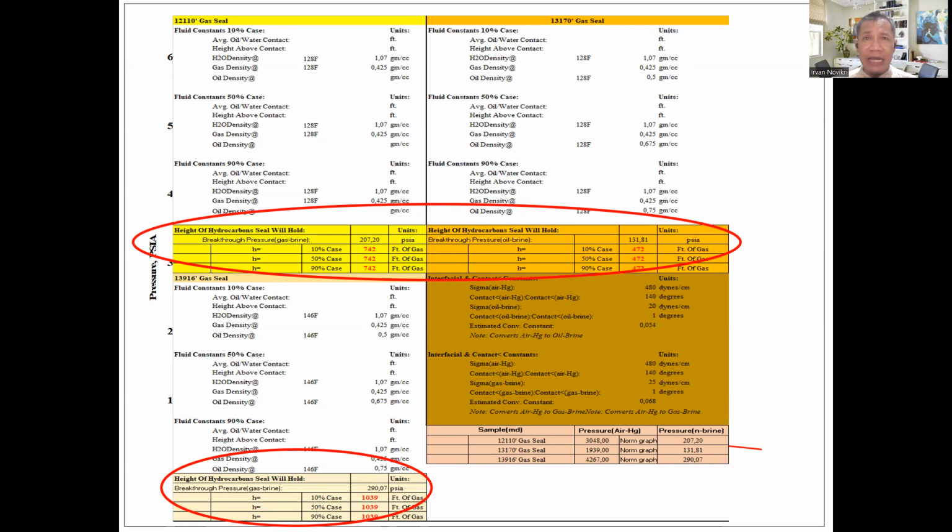Normally, a complete analysis also includes the pore throat entry radius, in microns, referring to the size of the opening or passage in porous material through which fluid can flow. It represents the radius of the smallest opening or throat that allows fluid entry into the pores. This parameter is important in characterizing the permeability and the fluid flow properties of porous media, such as rock.